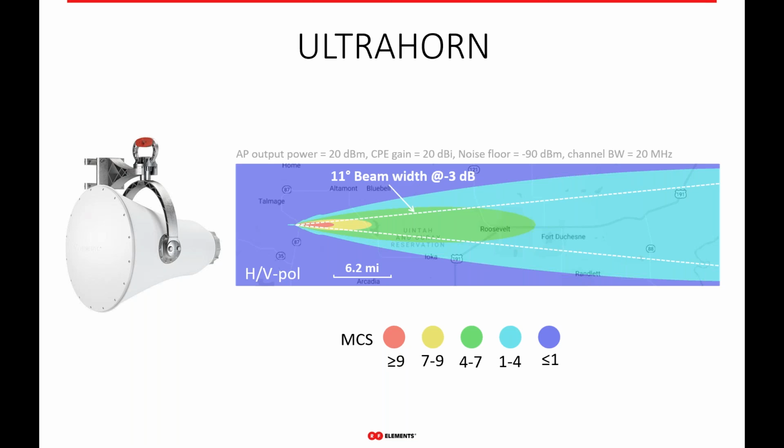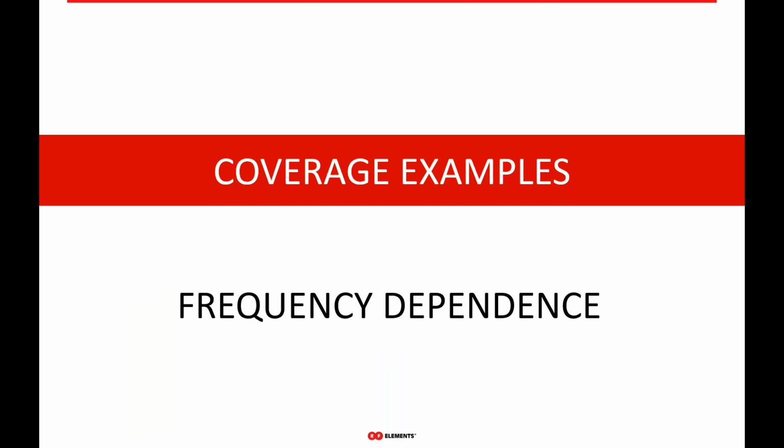Really important to note, one of the main parameters in designing all of our horn antennas is ensuring that both polarities match. This is a very difficult task, and we spend a lot of time to make sure that vertical and horizontal gain, vertical and horizontal beam patterns are as closely matched as possible, and in a lot of cases, identical.